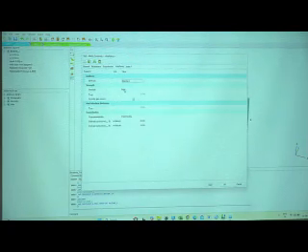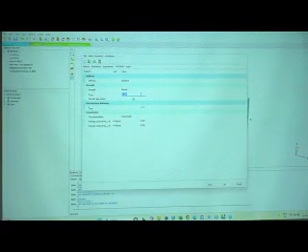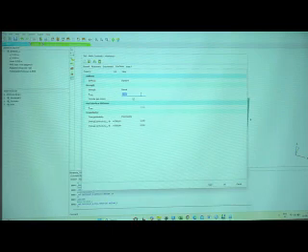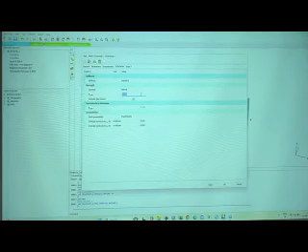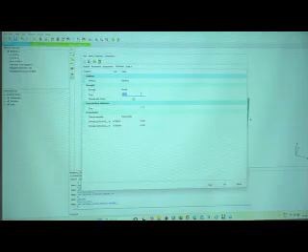Then the second important is this interface, R inter. If you put 0.7, 0.8, like in Abaqus we used 0.3. So 1 means the interface is very rough. 0.7 means 30% smoothness or 70% roughness is there. So you have to find this value through a direct shear test. Using the direct shear test, you can find the value of the interface between your concrete and the soil, and you can use that value here.